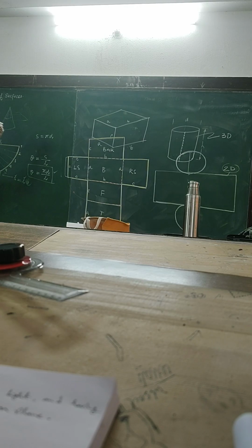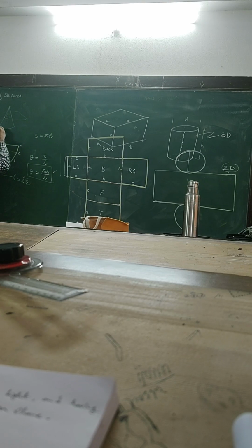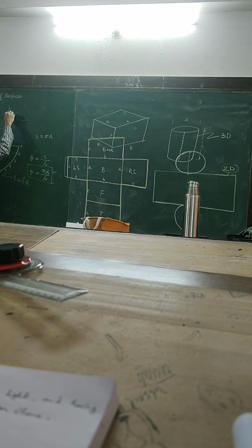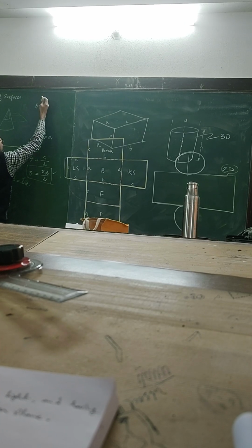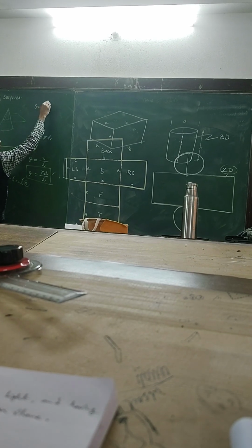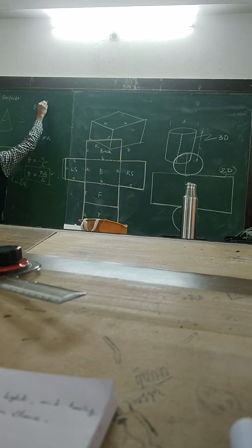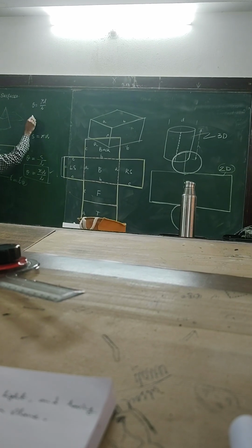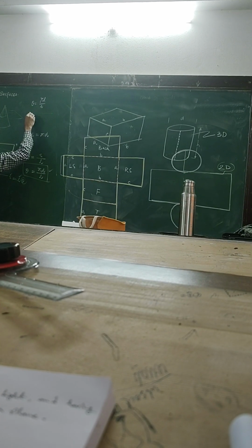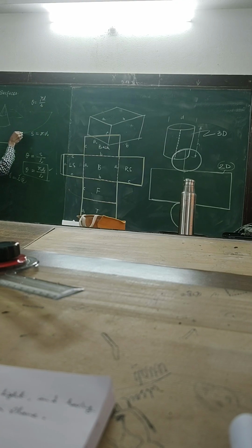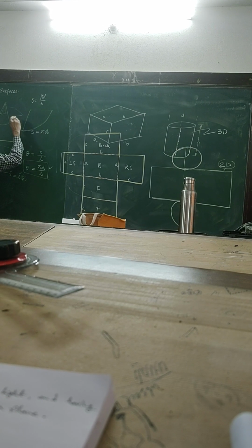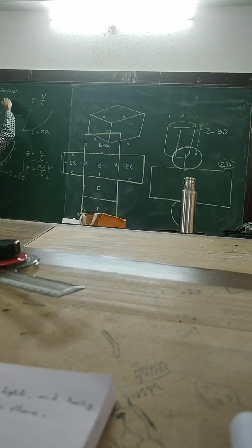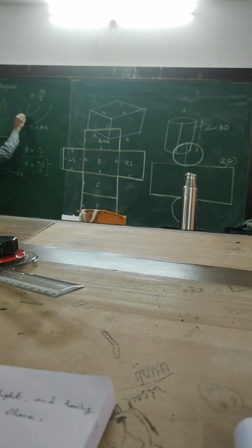That means for this case I simply have to know this pi d and I have to know this L, so that I can determine theta is equal to pi d by L, right? Pi d by L, and then we can draw the L length and then draw the angle. Simply draw the angle and take this length, then draw it.